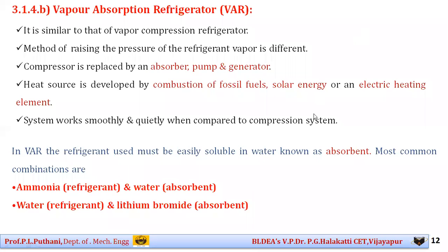So now you can use any one of the combinations. Please always remember, students, if you are using water as a refrigerant, then lithium bromide becomes the absorbent. If I am using ammonia as a refrigerant, then water becomes the absorbent.